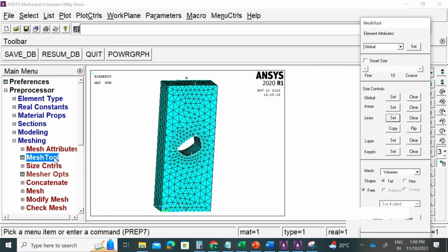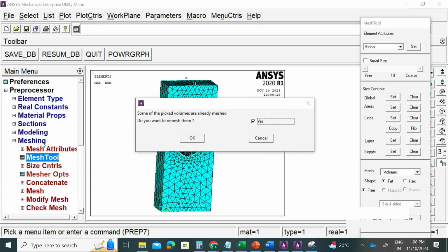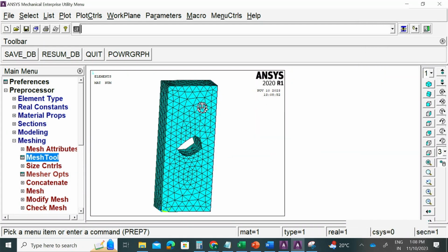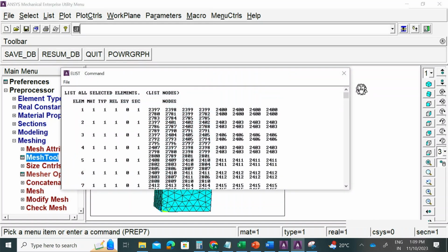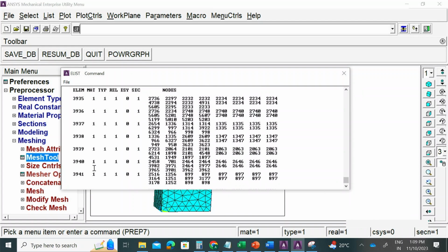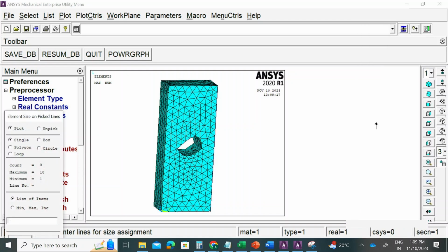Okay. All right, let's mesh this. Much better meshing, right? So let's see what it has led to. Basically, number of elements. Oh, it has decreased the number of elements. So that is something we do not want. So we want the elements to increase. So I'm going to just redo this one more time, because if the elements do not increase, we cannot perform the mesh convergence study.